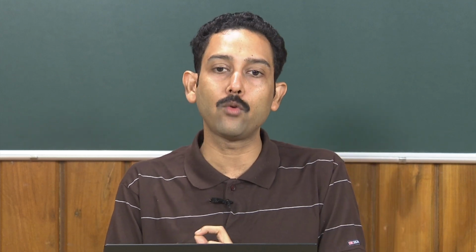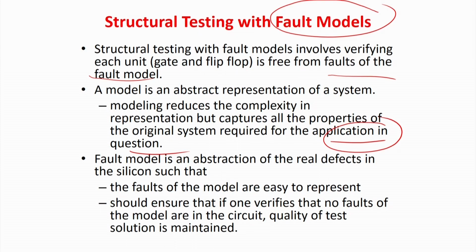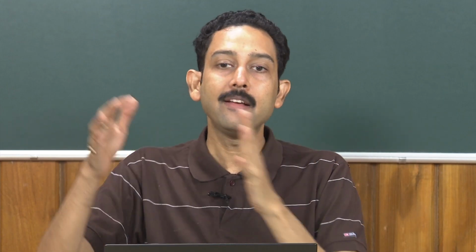That is, for the digital functionality of a circuit, what are the most likely fault models your circuit is going to suffer? Our application in this case is embedded systems operating in a digital mode of operation. So, what are the most typical types of faults my circuit can suffer from? I will only verify that my circuit does not have such faults. Then I can be more or less confident that the circuit does not have any problem.